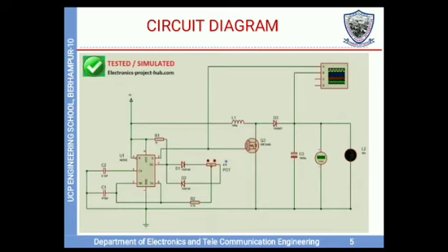IC 555 oscillator. The evergreen IC 555 is configured in astable multivibrator mode which oscillates around 30 kHz with the help of RC components connected around it. To control the output voltage, we need to control the IC 555's duty cycle. To accomplish this, two fast switching diodes 1N4148 are connected anti-parallel between pin 7 and a 47K potentiometer. By rotating the potentiometer clockwise and anti-clockwise, we can adjust its duty cycle and so the boost converter output voltage.